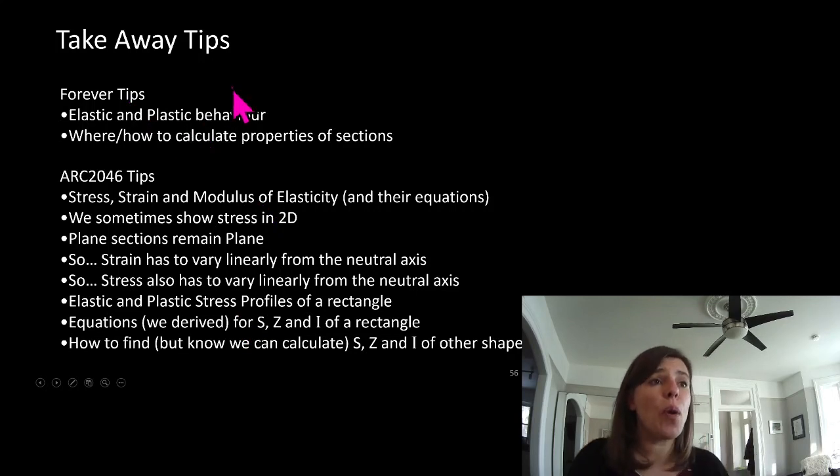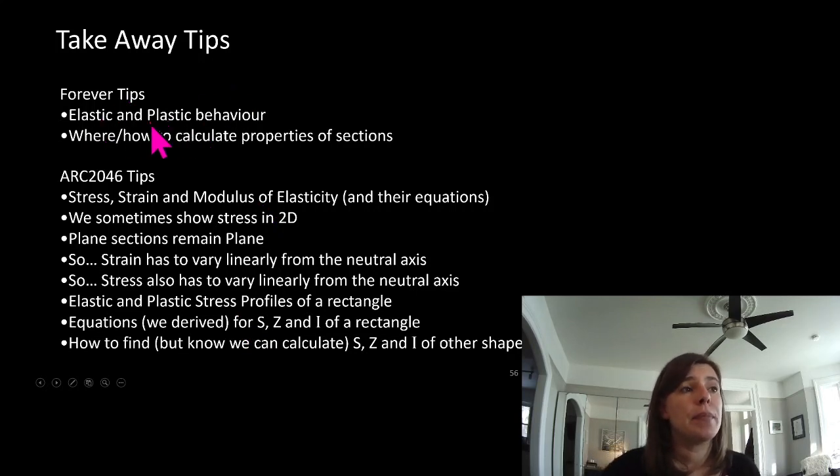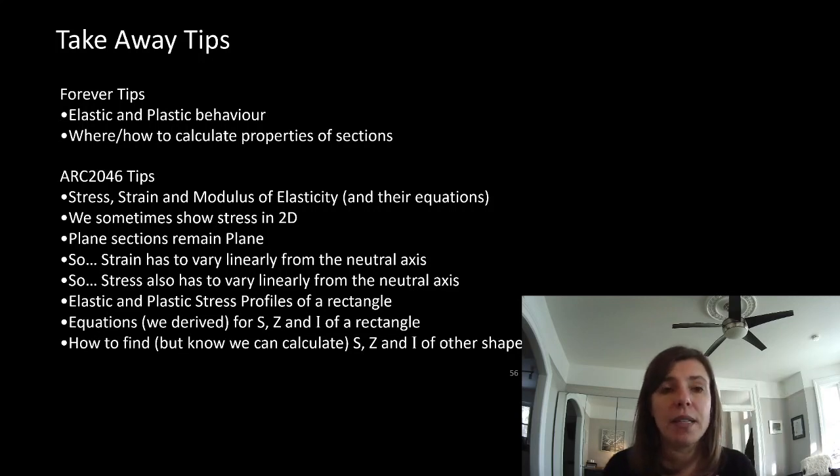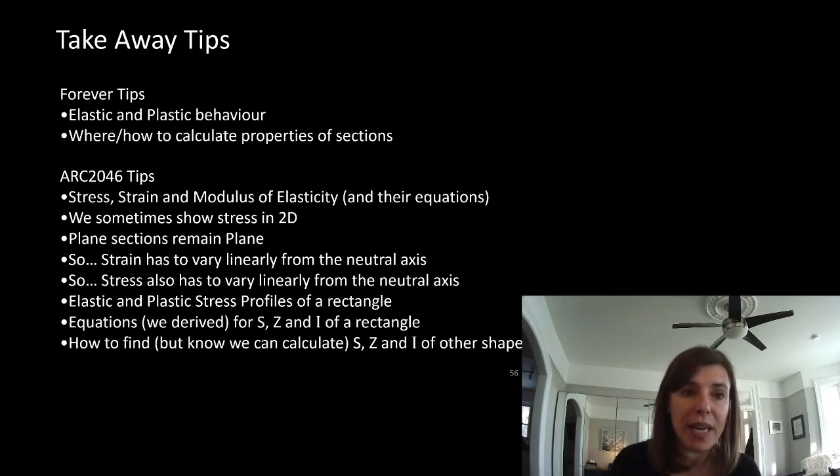So going forward, you should know a bit about elastic and plastic behavior, and you should know where and how to calculate properties of a section, and you should know length and depth are going to have the biggest impact on the structural design.